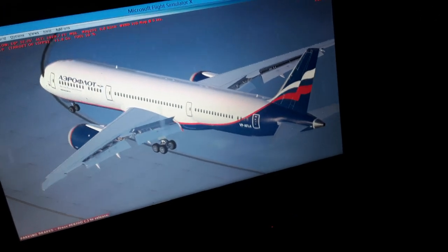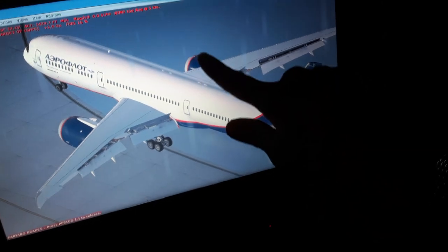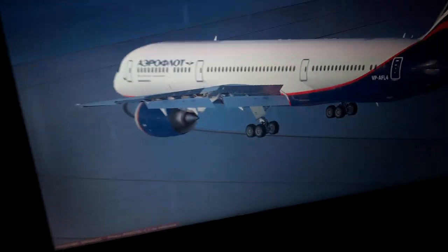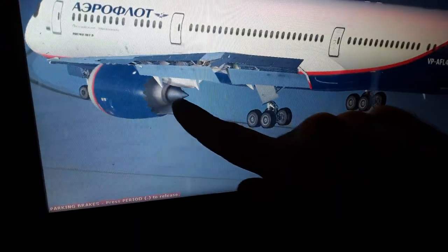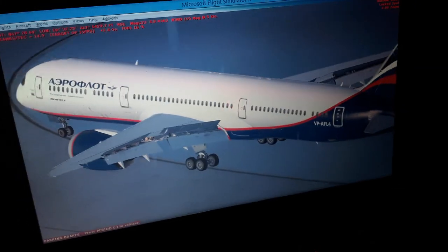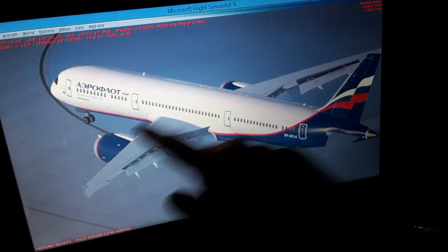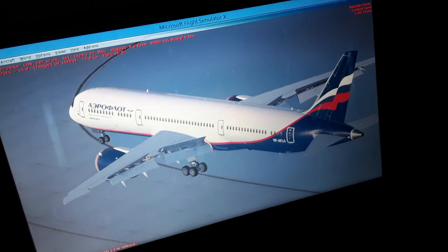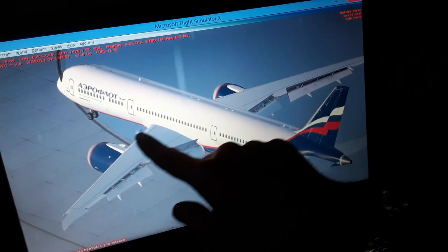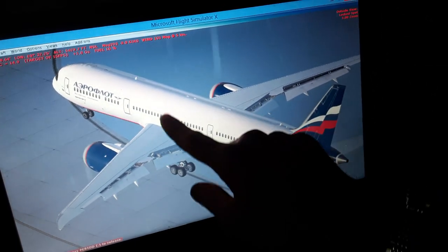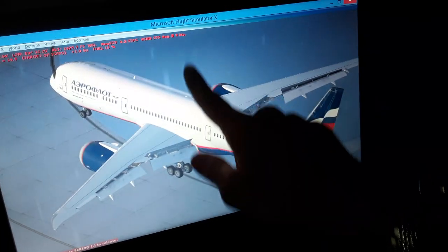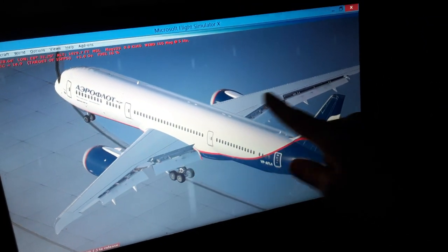So you can see here we have also the thrust vectors from the engines that move the aircraft forward. Over here the Z plus from the exhaust cones of the jet engines, as you can see. Also the bypass, we have the high pressure turbine and compressor, and low pressure compressor and turbine, and the front fan section over here. We can see also where the aerodynamic chord is. We have the left and the right wing fuel tank, and also the center fuel tank. And this is where the center of gravity of the aircraft transverses through the aerodynamic chord position over here.